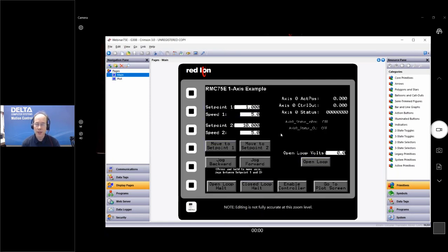So the items I've gone through cover pretty much everything: setting up tags, reading floats, writing commands, reading bits. I didn't talk about writing bits. Because the RMC does not support bits over the communications, it's rather difficult to write bits. What you can do is make sure you read the value from the RMC, modify just one bit in the 32-bit register, and then write it back again.